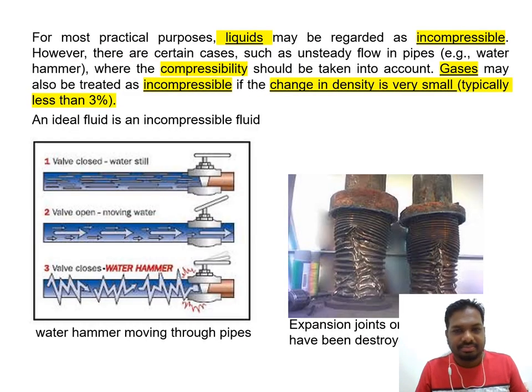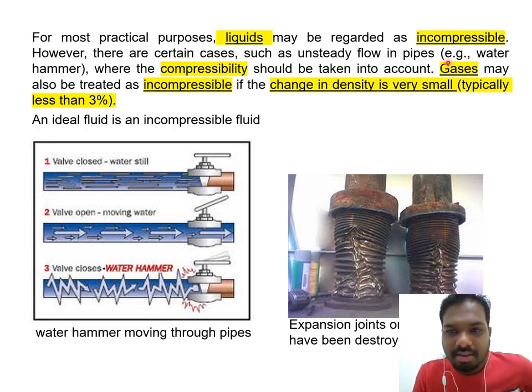So we can see that for most practical purposes, liquid may be regarded as incompressible. Mostly liquid is considered incompressible because it's already like semi-solid, so you cannot compress it much, but air you can compress. But there will be a situation we call water hammer. There are certain cases, such as unsteady flow in a pipe, where water hammer will happen and compressibility should be taken into account.